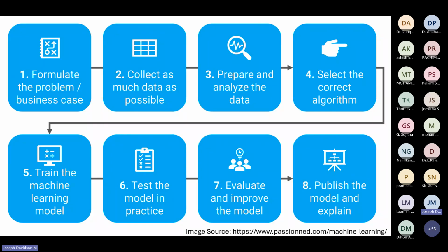So what we do is formulate the problem from the system. For this particular problem, I'm going to predict the grain size of a microstructure. So I will take a lot of samples, put them under a microscope, and take a lot of data. My process will be on one side. I will have a lot of process variables. All the process variables will throw up different sets of microstructures depending upon the process. I take that, collect as much data corresponding to the process, and then prepare and analyze the data.